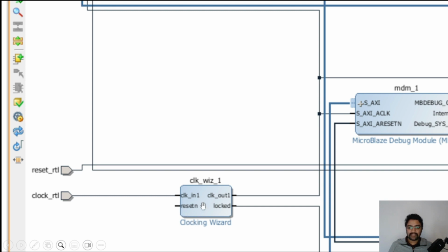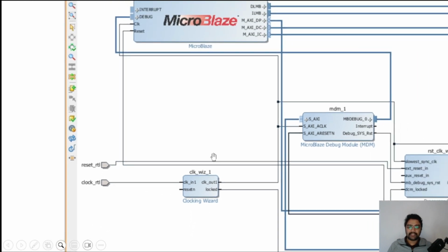Now this reset is left alone. We don't want two resets. If these are left alone, the architecture will understand that it has two resets. Why do we need two resets? That will obviously show an error, and one is a free floating wire. You shouldn't have any floating wires. And one reset we need to connect in the next window.